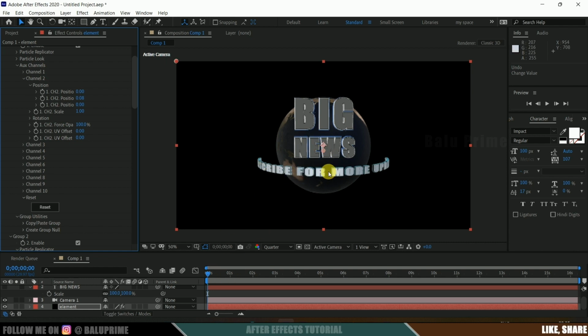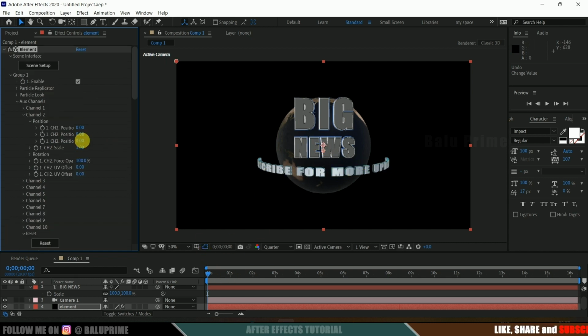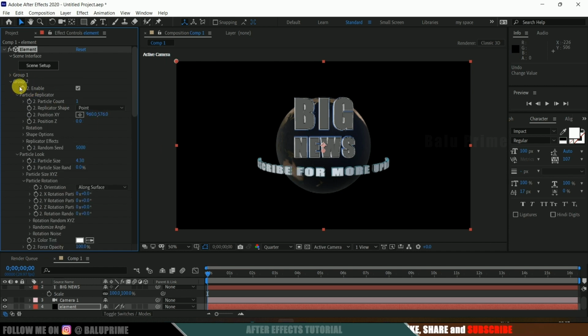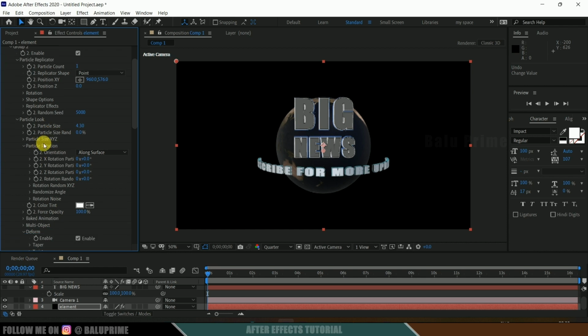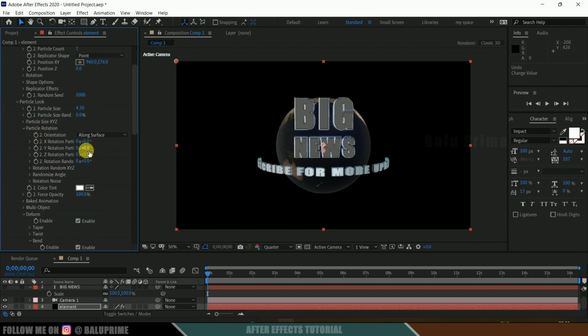So now let's rotate the text, this below text now. For that we need to work in group 2 since the text is in group 2. So close this group 1, come to this group 2. Now we won't be working with aux channel 1. So directly we will be rotating this text here. For that, come to this particle rotation. Here if I rotate this y-axis, you can see the text will be rotating here.